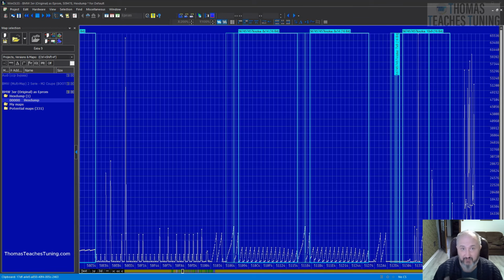So, our tuning must lead to predictable outcomes, of course, not just in terms of power and torque, but also regarding the appropriate air to fuel mixture, exhaust gas temperatures, or limitation of the back pressure. It's crucial to manage back pressure, for example, on a turbocharger to prevent damage, ensuring that these engines are reliable and operate under decent conditions without damaging them.